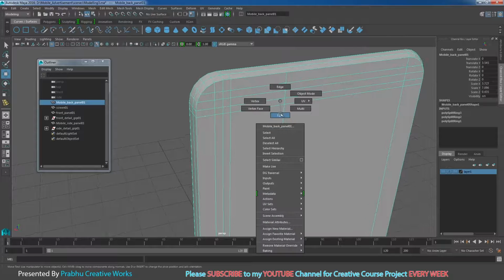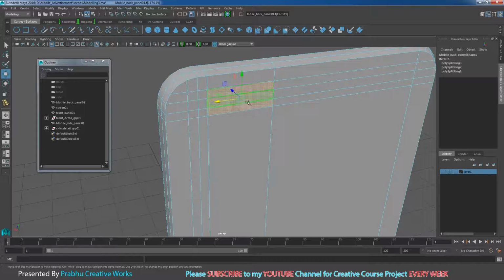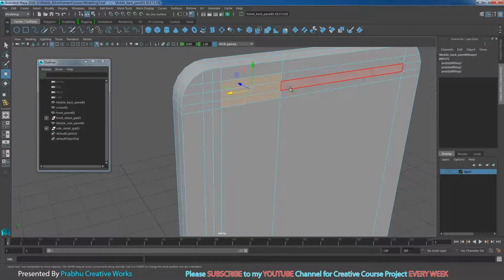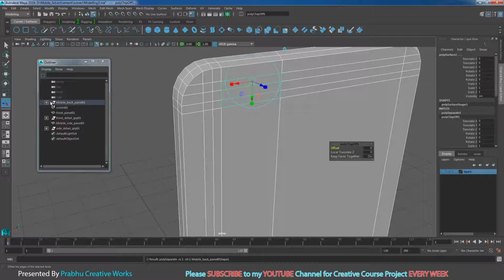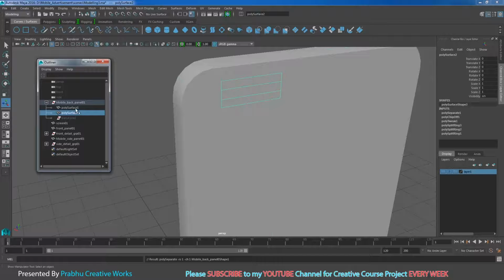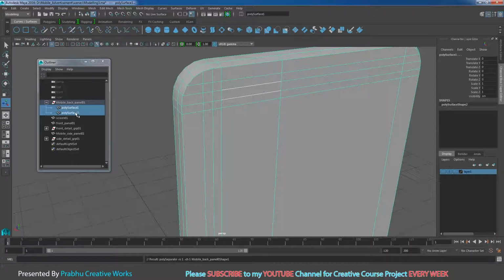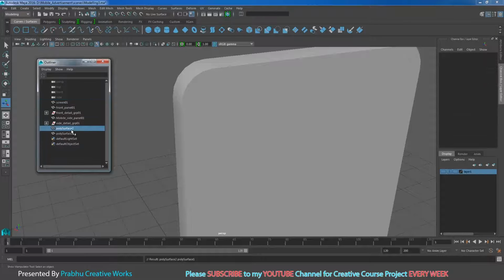So I will select these 4 faces. Right click and choose face and select these 3 faces over here. Don't select the top part. Now we want to go to edit mesh and choose extract. So expand this group, select both objects, go to edit, delete by type and choose history. When the 2 objects are selected, press shift P on the keyboard, so that means it will leave the group. So I will select my empty group over here and press delete on the keyboard. So I will have these 2 objects.